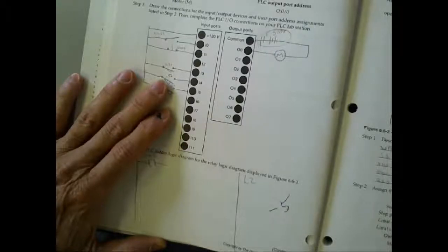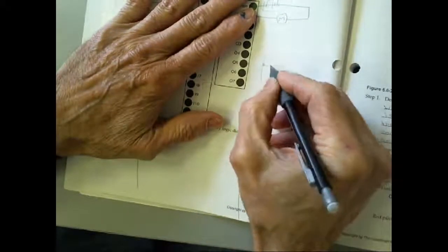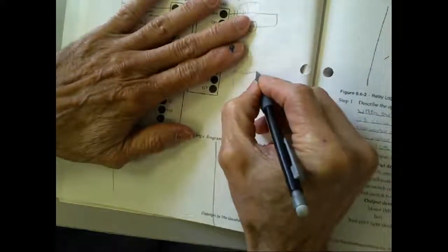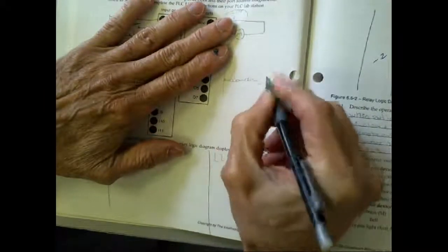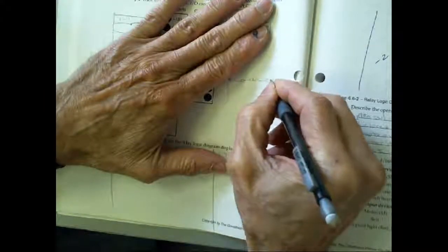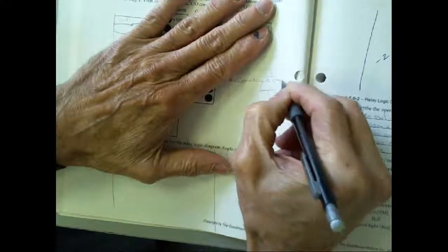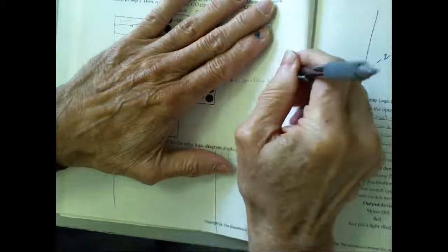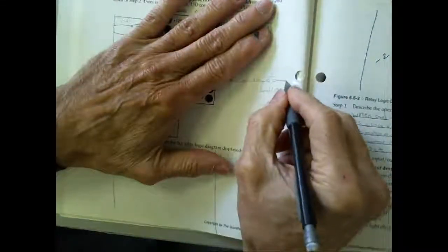Normally, your E-stop circuit is not a program circuit. So somewhere we might have a circuit that looks like this. And we could have multiple E-stop buttons, guys. And then we would come over here and have a reset, and then an E-stop relay. I'm drawing it as a light.